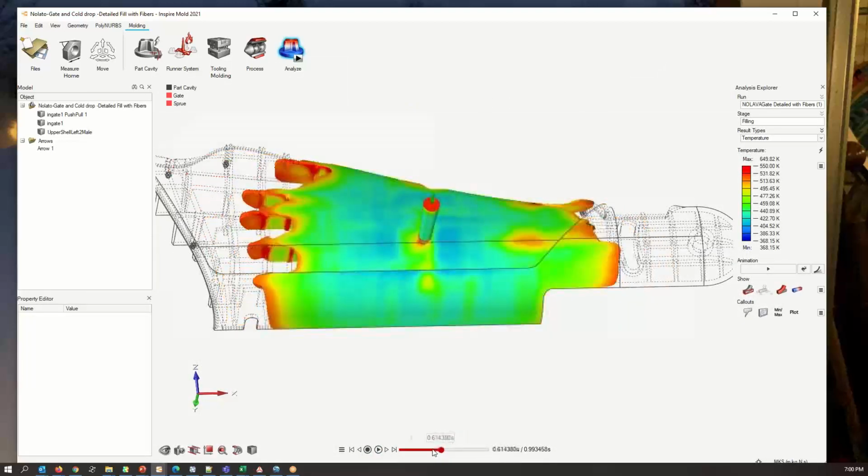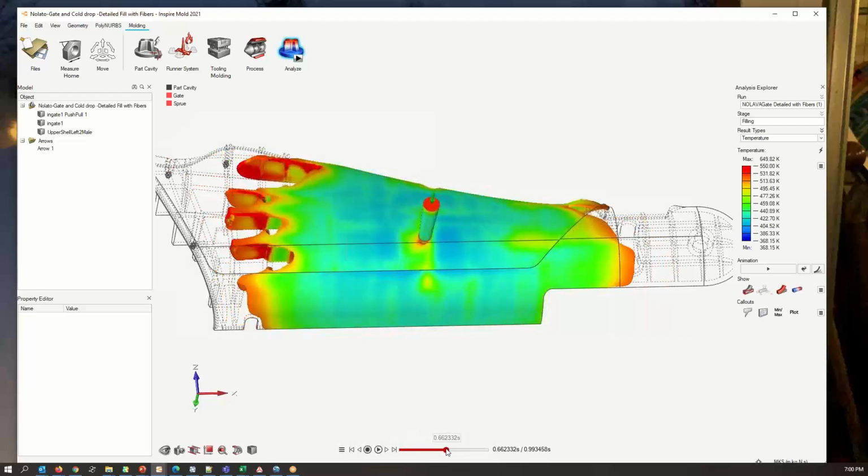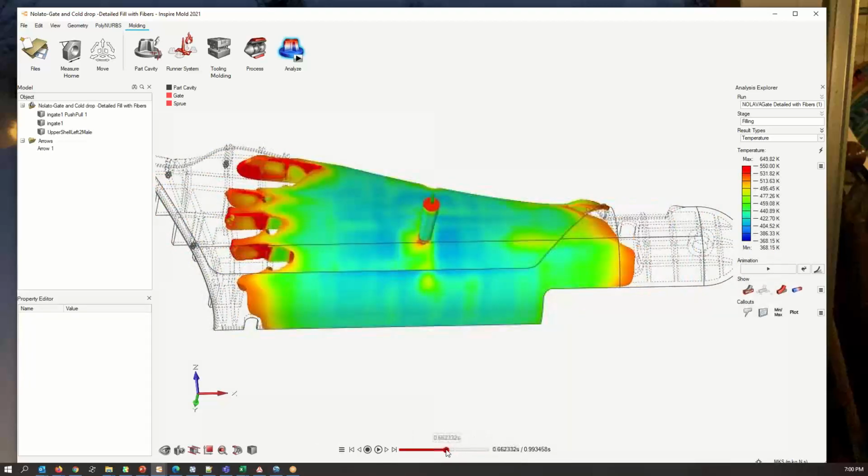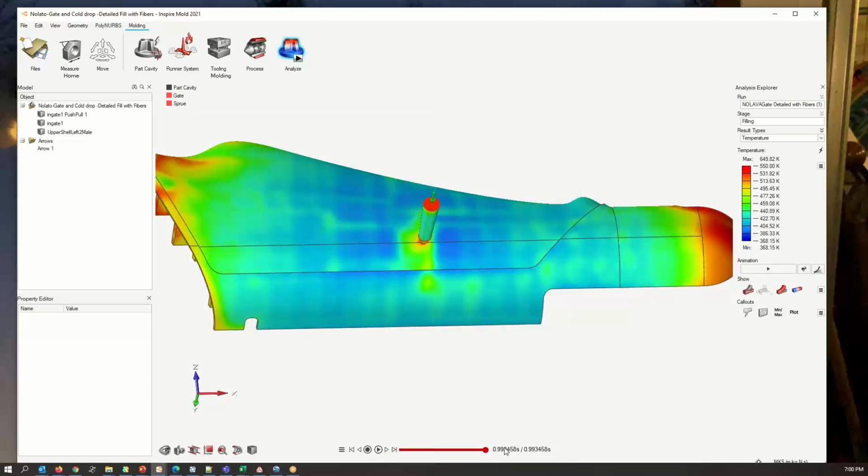And this is why I start saying things like, maybe you want to investigate putting pins in and venting from, say, some of the ejector pins in your parts. That is a viable form of venting. As long as you can get the air out, it works.